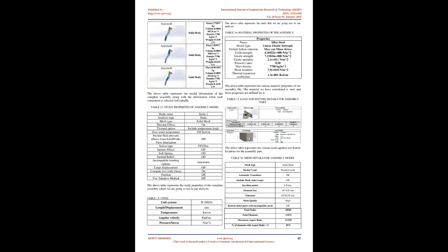6. Mates applied in assembly. Rotate LINK2 by 3 degrees clockwise about the base. To do this we will impose a rotary motion to LINK2 at the location of the concentric mate, simulating the pin connection with the base. The angular displacement needs to be achieved in 1 sec and we will use a step function to ensure that LINK2 rotates smoothly from 0 to 3 degrees.